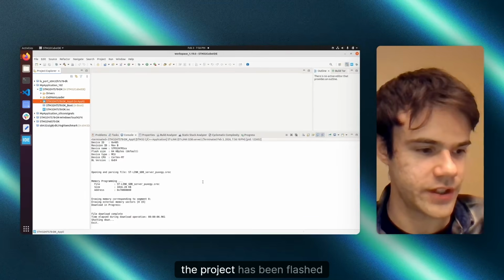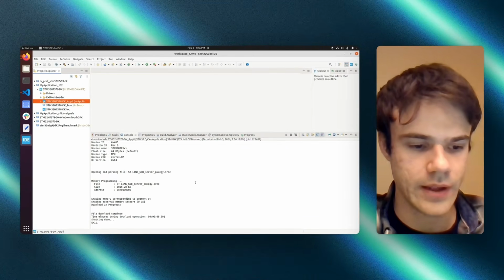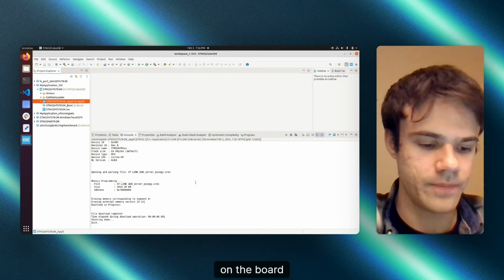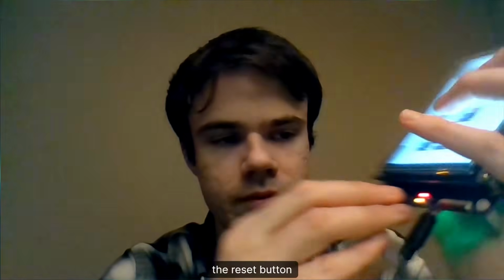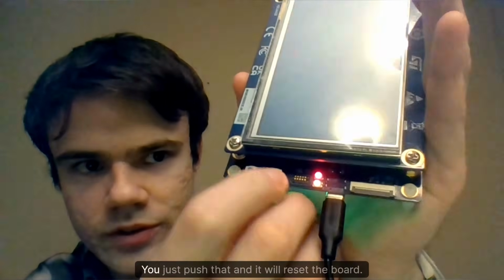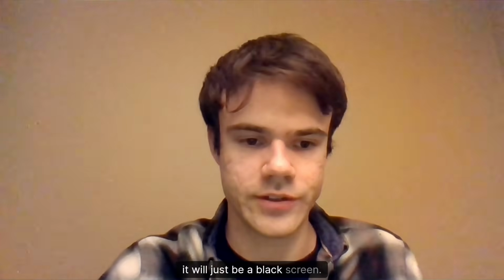After the project has been flashed, it's important to note that you need to push the reset button on the board or remove power and restore power. So the reset button is this black button here. You just push that and it will reset the board. Until you do that, it will just be a black screen.